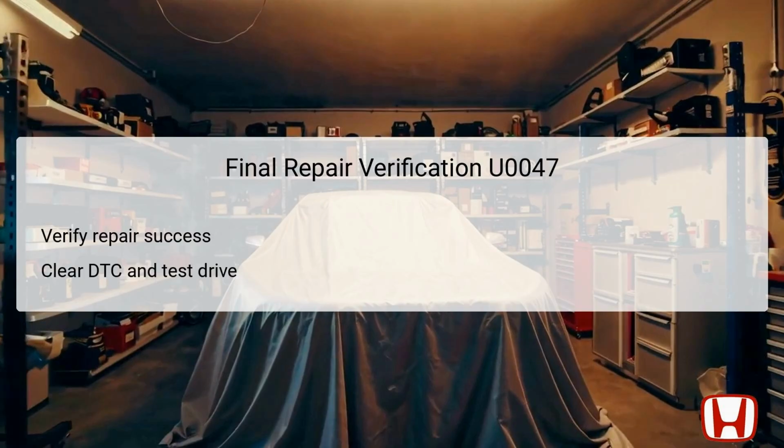After completing all relevant repairs for DTC U0047, it is critical to conduct a final verification to ensure that the issue has been resolved. Begin by clearing the DTC to reset the vehicle's diagnostic system and eliminate stored faults. Following the DTC clearance, take the vehicle for a test drive in various operational modes, monitoring the performance of both the gauge control and infotainment systems.